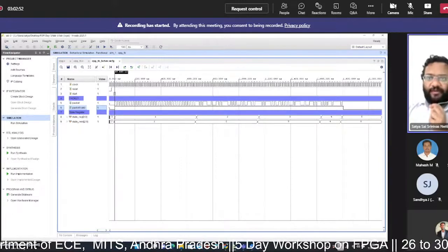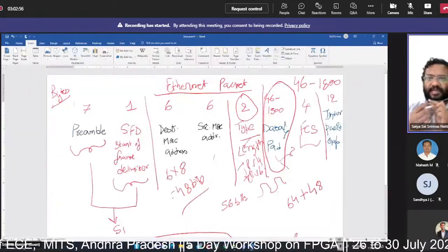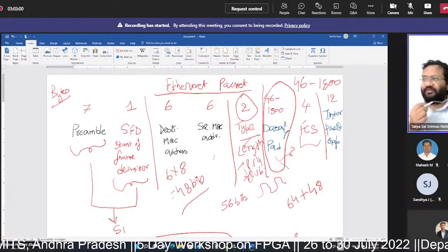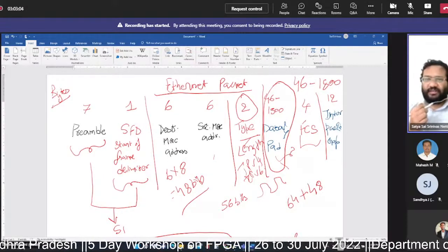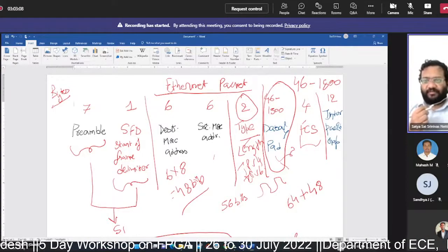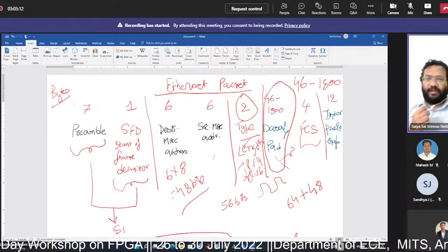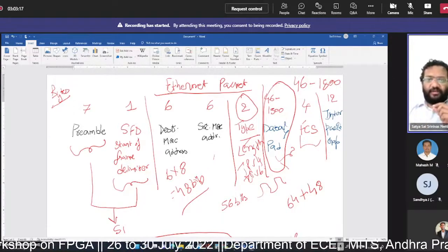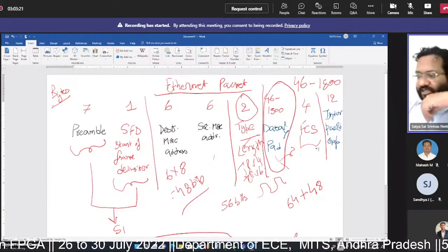So a minimum of 46 bytes, or up to a maximum of 1500 bytes. In my example, I have constructed the FIFO so that a minimum of 46 bytes of data can be stored. I read the data byte by byte, and then transmitted the data on the packet output. After that, there is a frame check sequence.